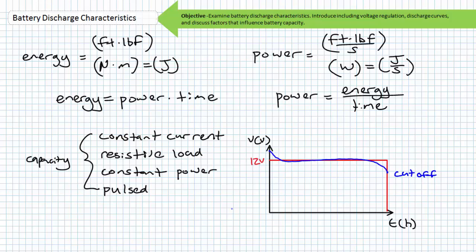If a battery delivering power at a certain rate stays in the fight longer, it delivers more energy. Energy is power times time. This is essentially the logic behind the amp hour capacity rating of a battery. It basically ignores voltage variation of the battery, and a user is left to assume a nominal value. As previously demonstrated though, increased current draw will ordinarily reduce the working voltage of a battery, so the nominal capacity of a battery in units of amp hours can be viewed as a single snapshot of a moving target.